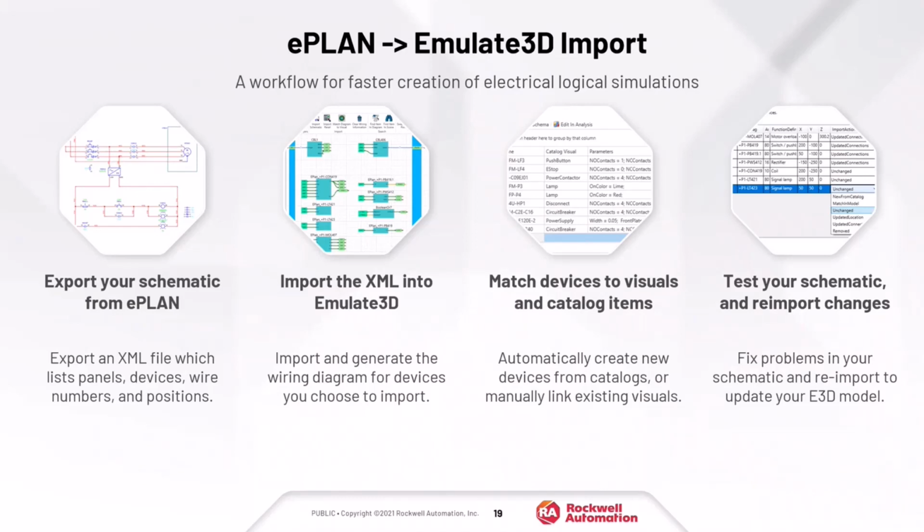You can hand that XML file to the Emulate 3D engineer, who can import it, and 75, 85, and depending on how accurate you are, even up to 100% of the wiring diagram can be recreated automatically inside of Emulate 3D, which really saves the designers a lot of time. And the logic is technically already there, so you know what is wired to what.